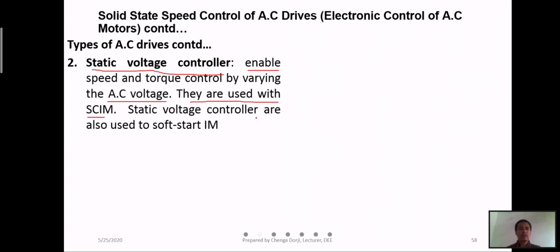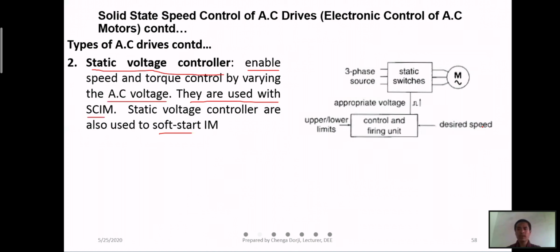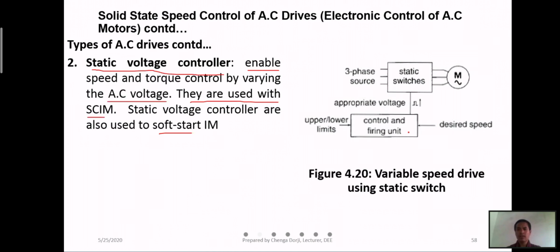Also, the static voltage controllers are used to soft start the induction motor, which means you can use them as a starting method for the induction motor. So this is another one. Again, the desired speed is given, then the firing angle is given to the switches.